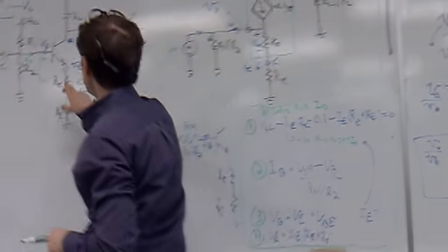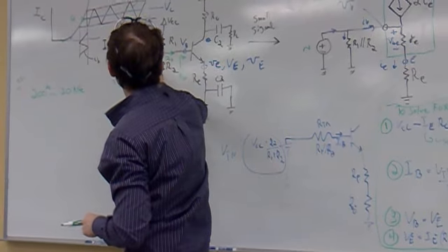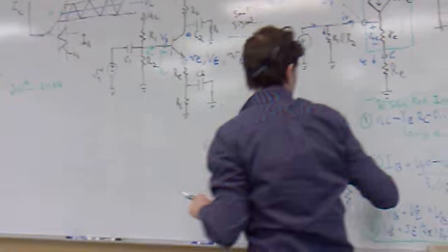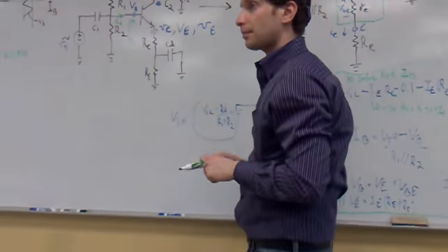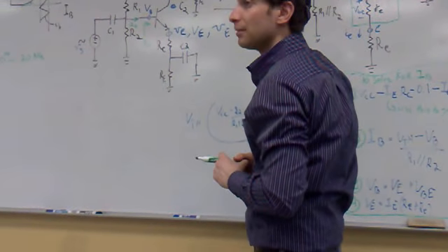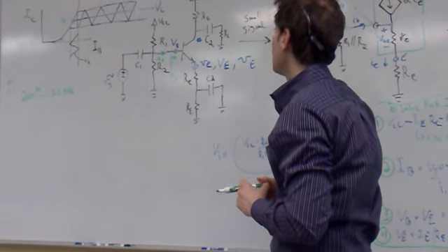It's going to equal R2 over R1 plus R2, which is the voltage here. DC now. We only care about DC. So that's V Thevenin. I'm calling it V Thevenin because it's easy. But that's equal to VB? Not necessarily. No, but we find VB with this formula.